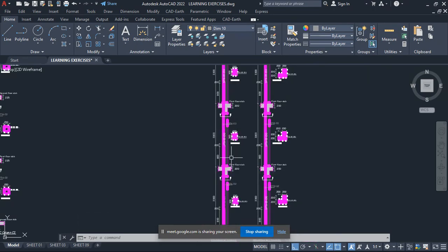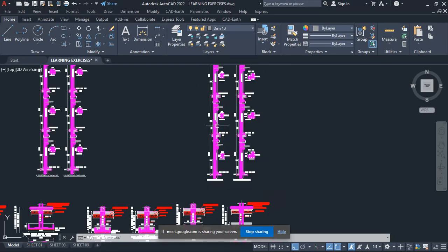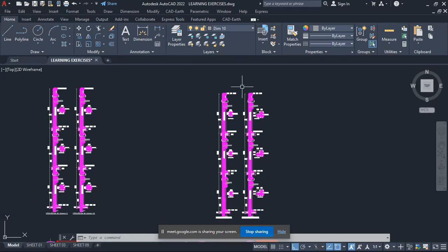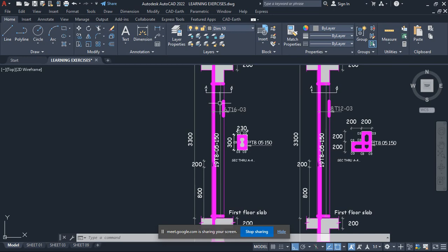No, I'm okay. Now the challenge with these, if you want to check per level, because you may have a column of like 10 floors, it means you may be forced to get the different moments at each level, if you don't want to provide uniform bars throughout.